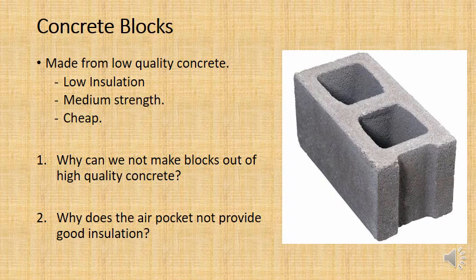So it needs to be a lower quality concrete to get the absorption capacity high enough that the mortar will actually stick to the block. So that's why it has to be cheap, low quality concrete for a concrete block. But of course that lowers the insulation and it also lowers the strength.